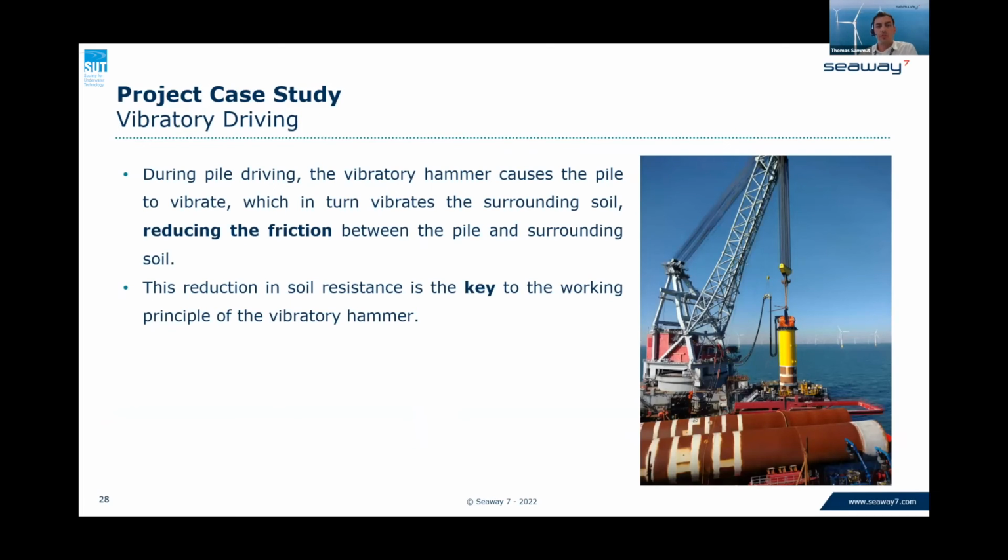So what is vibratory driving? Once we bring the monopile vertical, we lift it into the gripper that I mentioned earlier, and after setting the pile down onto the seabed and letting it find its own self-weight penetration, we can then run the vibratory hammer. And the principle there is by vibrating the pile, that then reduces the friction, liquefying almost the soil immediately around the pile.